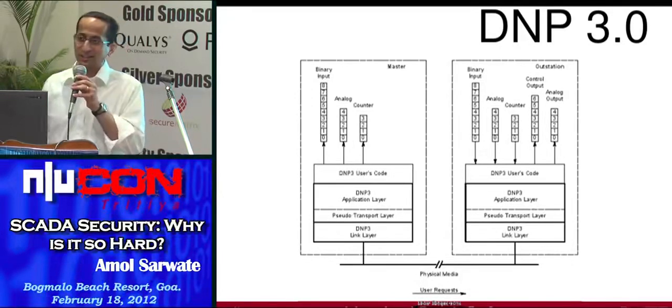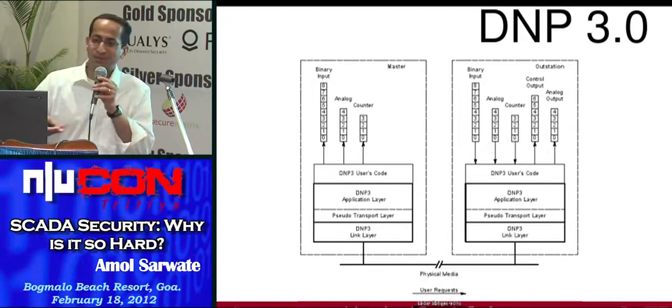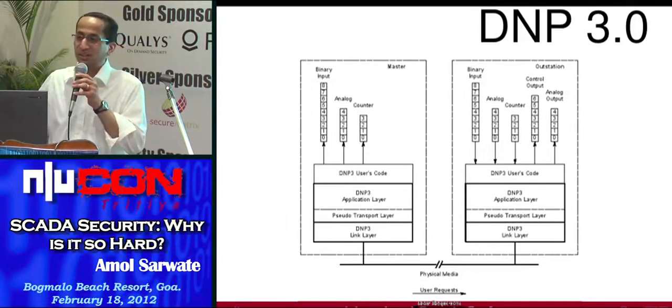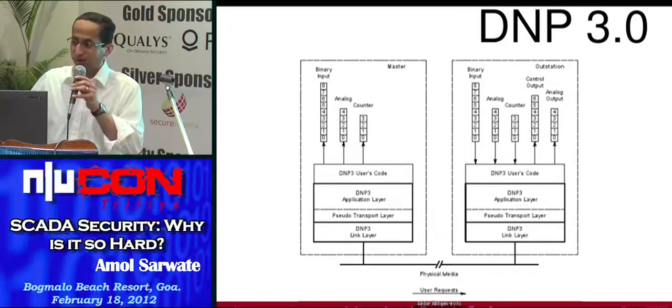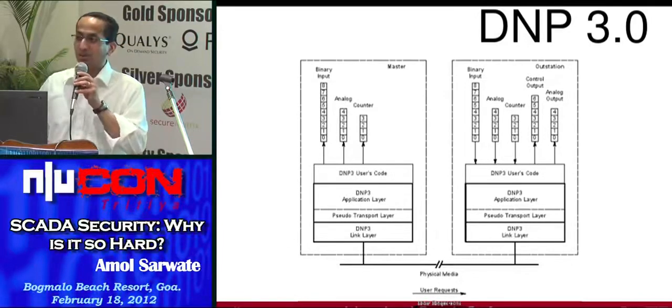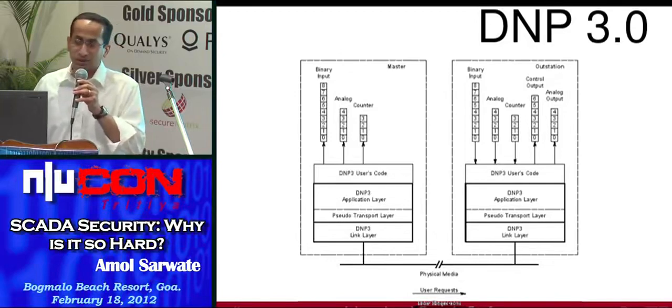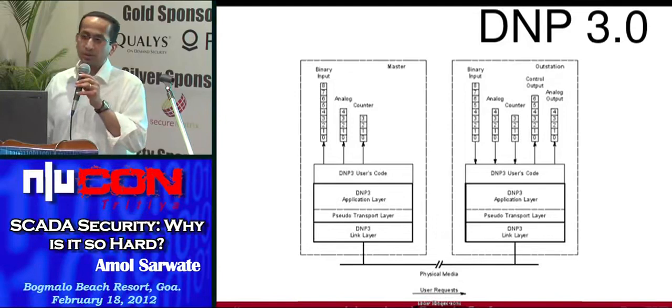It has timestamps. In Modbus, if you say, give me the temperature, it gives you the temperature, and you assume it's the temperature for right now, but you don't know the precise time. The electrical industry couldn't do without that.